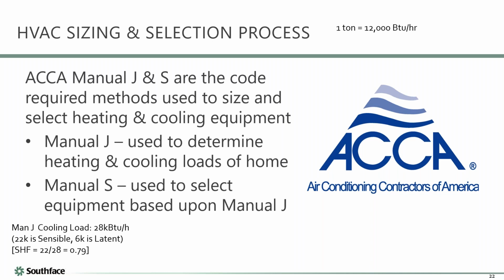Okay, so then you go to this manufacturer's line of equipment. Most people would say that's a nominal 2.5 ton air conditioner right here. It's a 2.5 ton air conditioner because a ton is by definition 12,000 BTUs an hour. Joey, where does the term ton come from? It has something to do with ice, if I recall correctly. Exactly. A 2,000 pound block of ice melts at a rate of 12,000 BTUs an hour. So it comes from pre-refrigeration days.